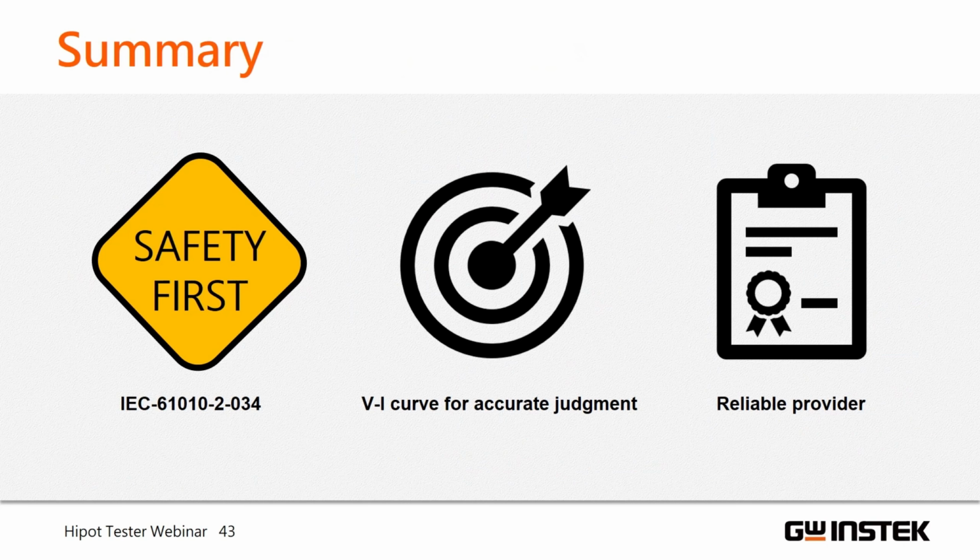Now, let's summarize in 3 points. First, ensuring safety should be the foremost consideration when using a Hipot tester. Therefore, the Hipot tester must comply with IEC standards. Second, the tester must have the VI curve function to accurately detect insulation breakdown. Third, the provider must offer reliable support.